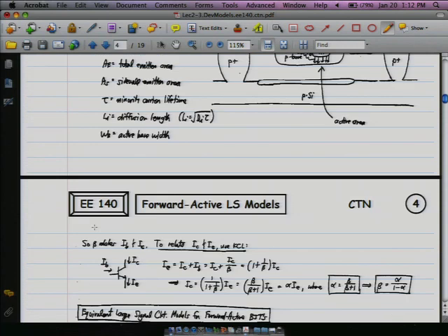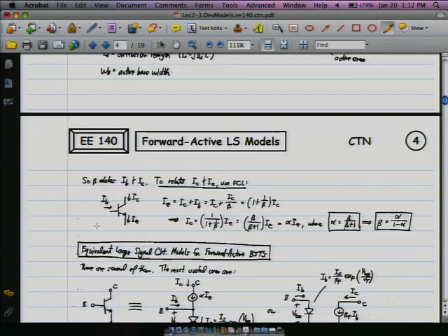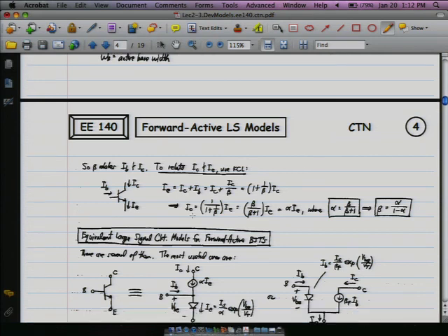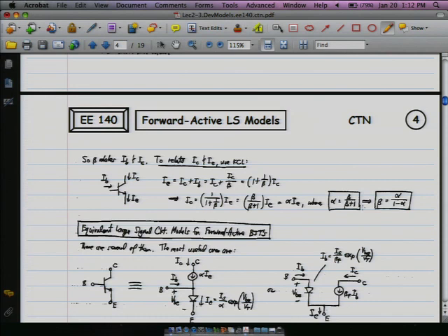Okay, so now we start getting into more of the true circuit stuff, where we come up with all these various parameters. Oh, actually, before that, there's one thing. We had this beta to express the current gain. There's also a factor alpha that expresses the current efficiency. And it's pretty much interchangeable with beta. If you have one, you have the other. It's sometimes a shorthand in different expressions that is a little easier to write, but the vast majority of the time we'll be working with beta.